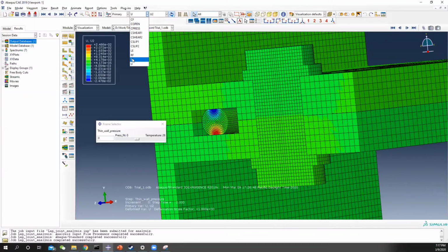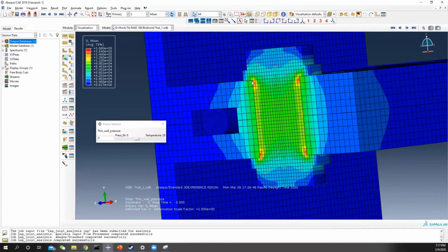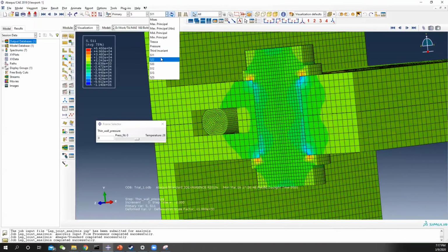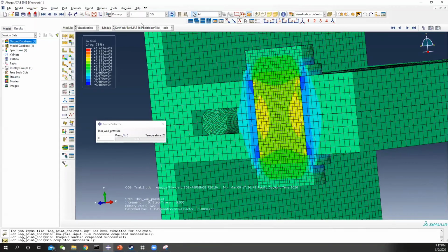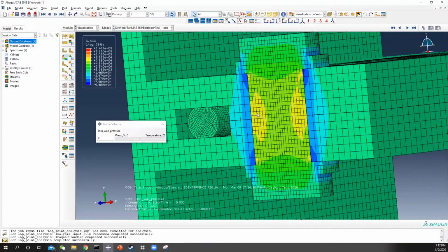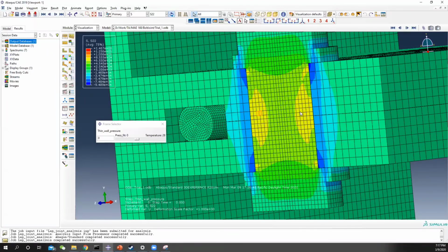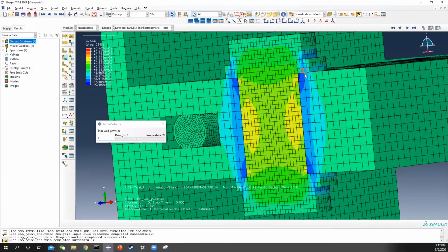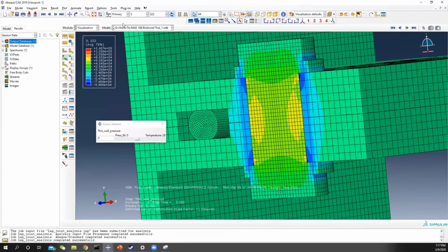If you look at the stress, you will see stress concentration on the corner. And if you look at, for example, the shear stress here, and also all the stresses, the corner of the bolt should have the largest. Other than that, this is the tension. You have the tension here and compression for your geometry at the washer because of the preload inside the bolt.